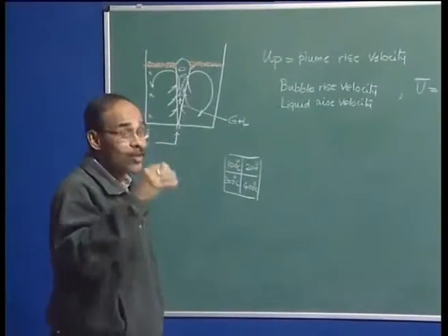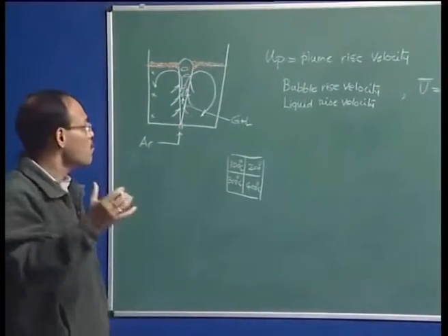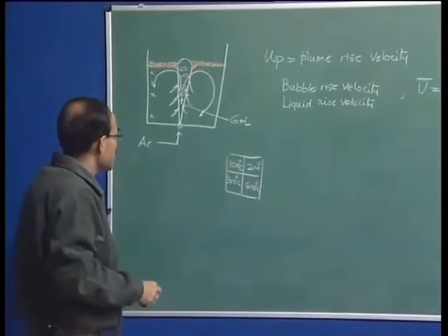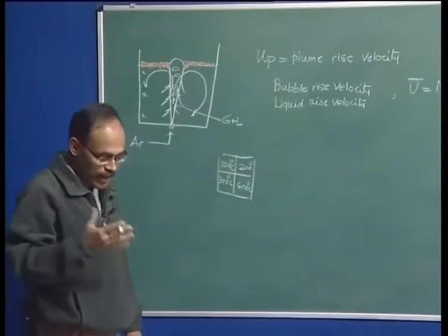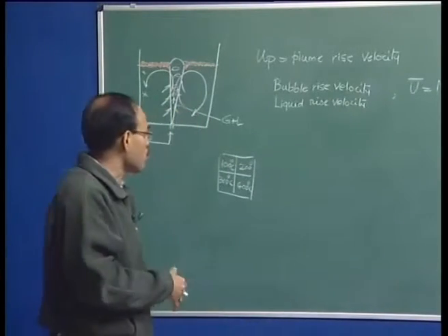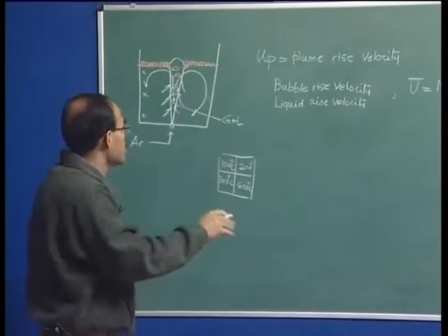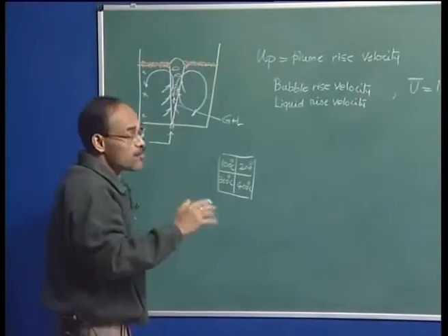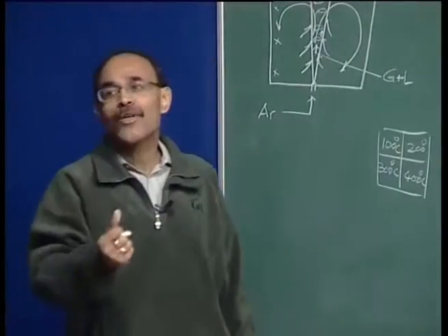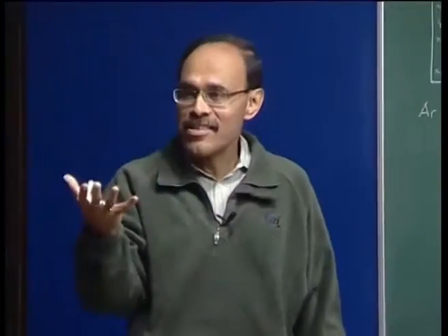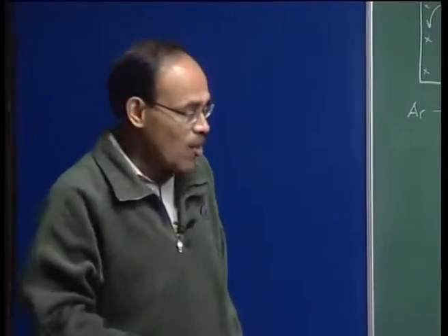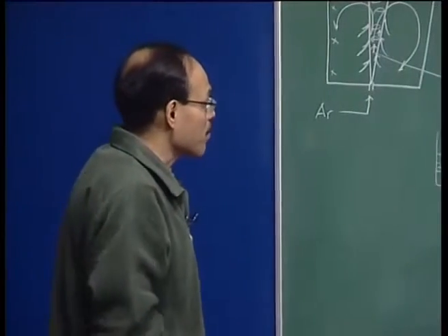Therefore, the convection current is going to assume predominance in such processes. So mixing, mass transport, alloy dissolution, temperature distribution, convective heat and mass transport, everything is going to be a function of the velocity, and that is why we have to have some idea of the velocity scale in the system, and then only we can conclude whether the argon stirred system is really efficient or not in terms of its processing capabilities.